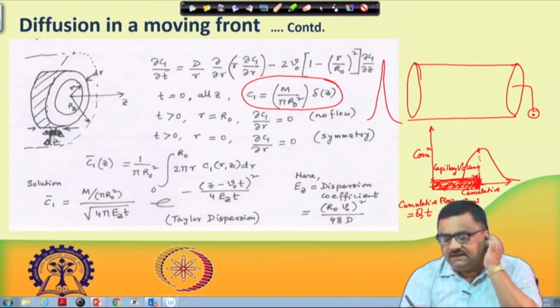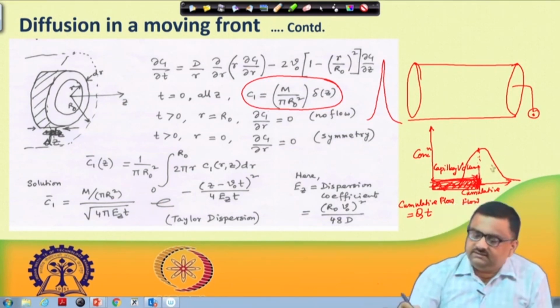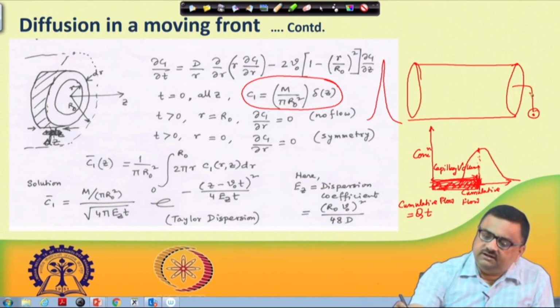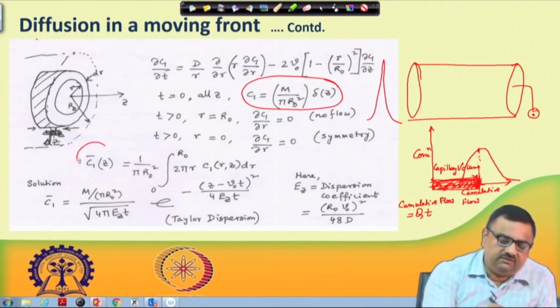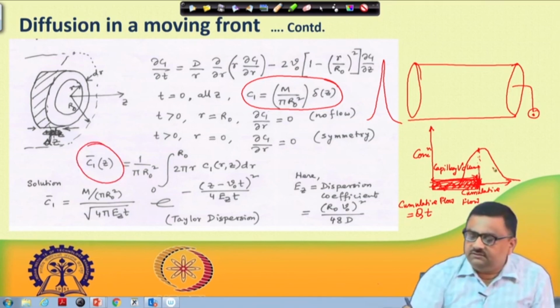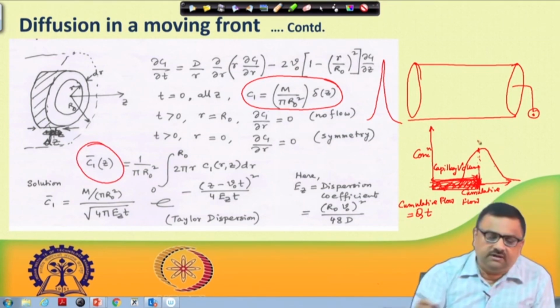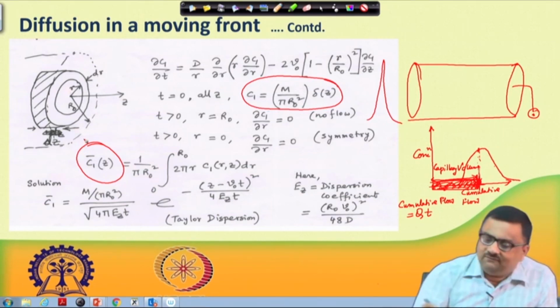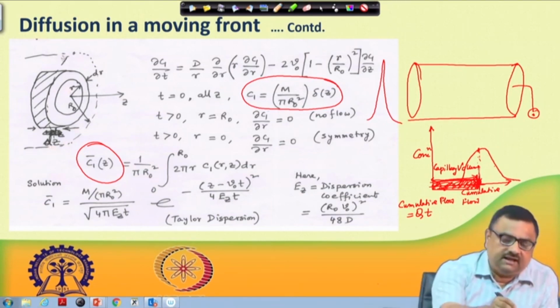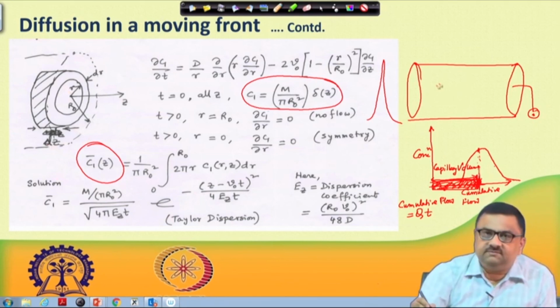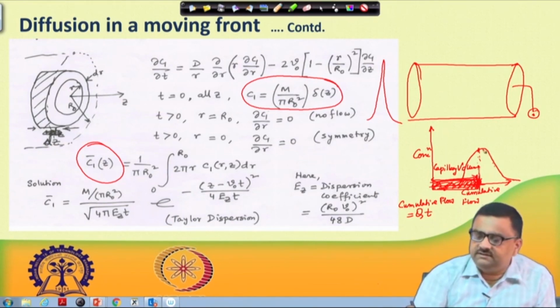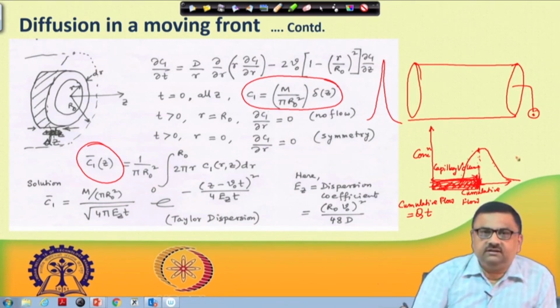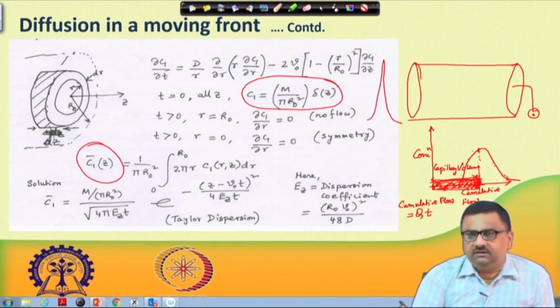What you are plotting here, this concentration that we are getting, is basically this average concentration C1 bar. Because we are not getting concentration at different radial points, but we are getting an average concentration for this slice. As I said, we picked up slice by slice. So, this concentration is the concentration of each slice. This is something which we can get at the outlet.